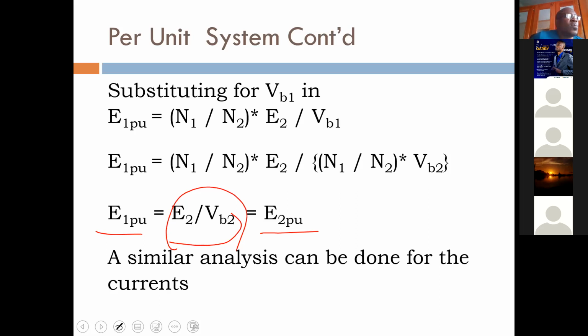When we try to put up small businesses in residential communities, we are wreaking havoc on the power system. And we think the utility just wants to know what is happening in order to increase charges. But it's not so. It's just based on the fact that we're rating it on MVA. And of course, the lower the power factor, you need more MVA to supply the amount of megawatts. All of that fancy jazz.